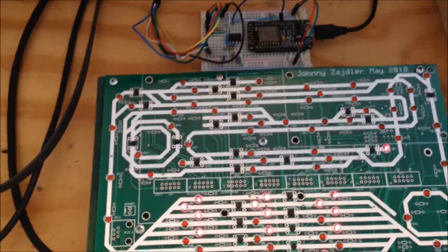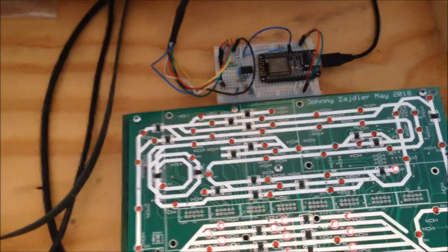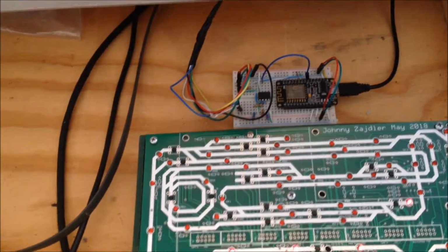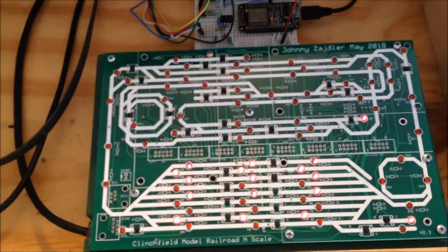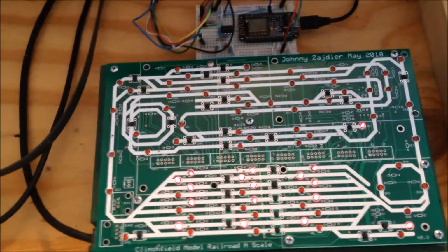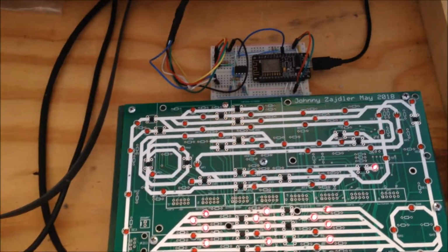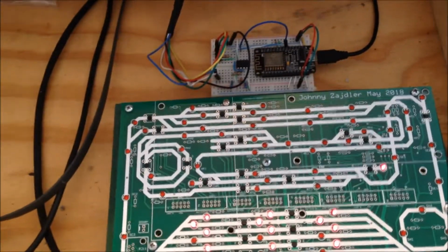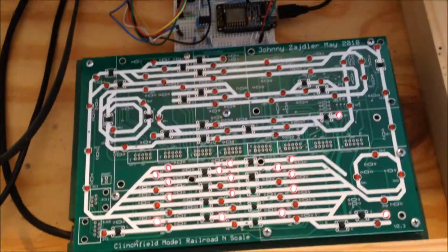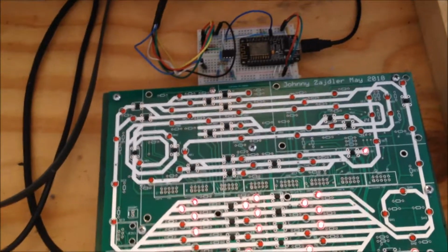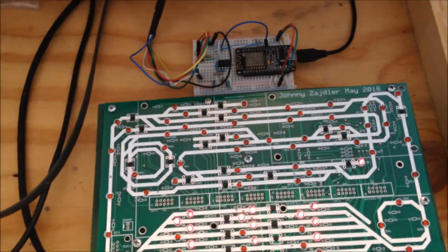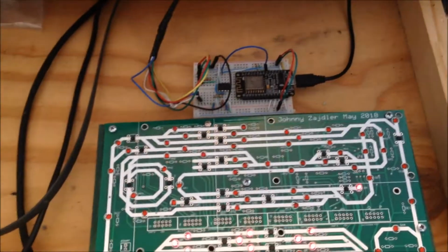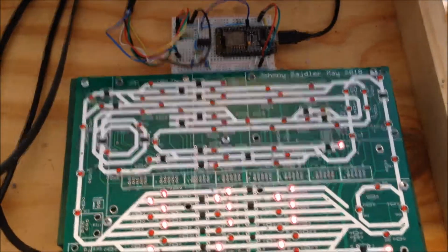So you have the LocoNet connection and LocoNet feedback. There was also a technology that was around for like 15 years or so, maybe longer, called S88, and that's another feedback type of protocol, but it's not as advanced as LocoNet. But you can actually build circuits for your layout that cost $5–10 for block occupancy, and it'll tell you where the trains are on the track and stuff like that. But anyway, it has a few little disadvantages.